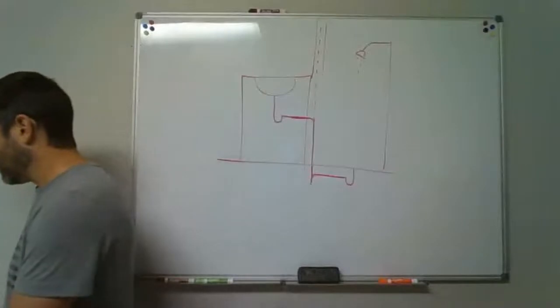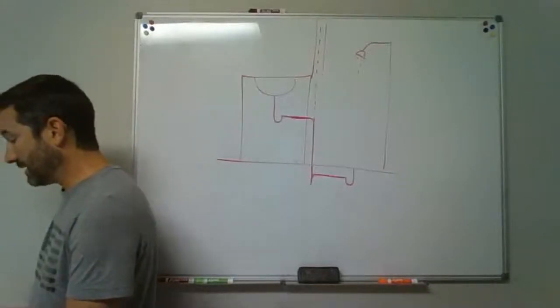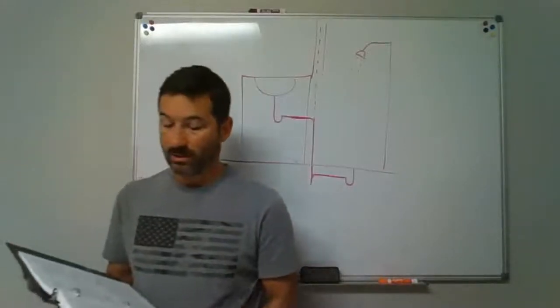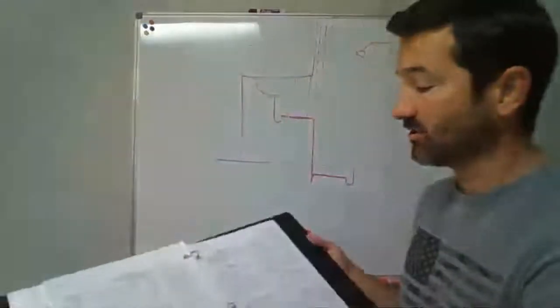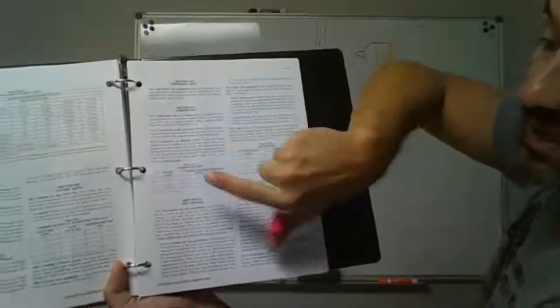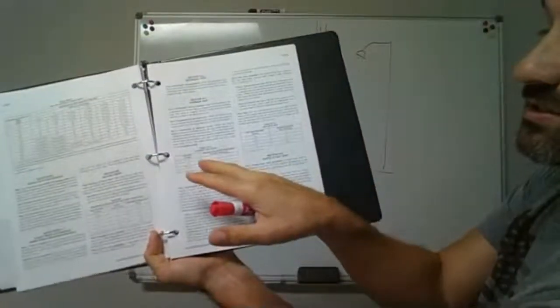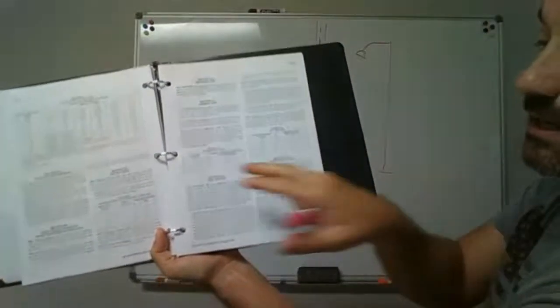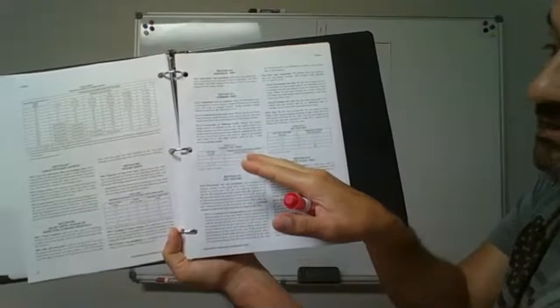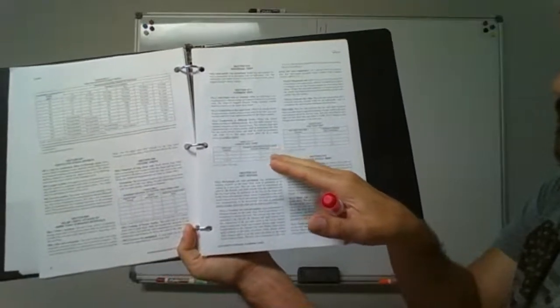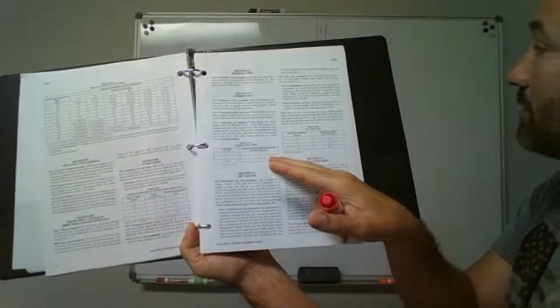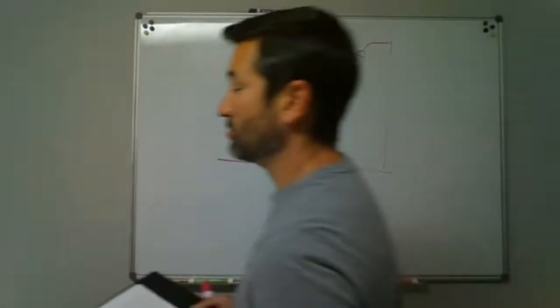Now, when you connect at different levels, 911.2 addresses the connection at the same level, and 911.3 addresses connection at different levels, like what we're doing here. The next one is the common vent sizing. It gives you a little chart of pipe sizes and the maximum discharge from the upper fixture drain, the DFU value here. So what you do is you take those numbers.